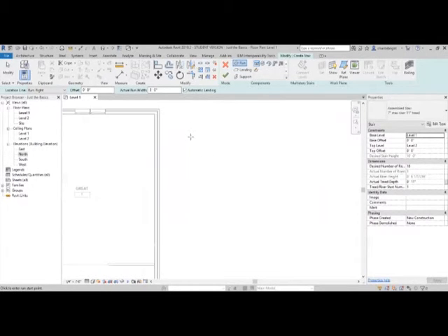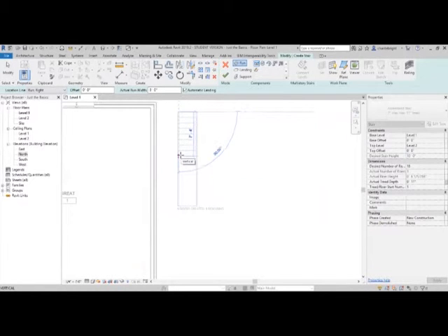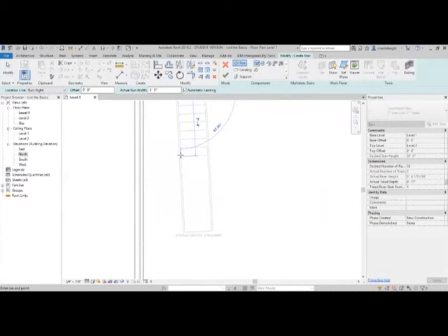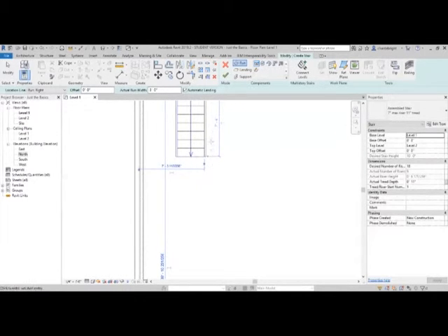So if I want an L-shaped stair, it's just as simple, and you can change where you run. I'm doing this very, very fast just to show you the different methods. I'm going to click, and I'm going to start it out. And you'll even see, right underneath the bottom, it says 9 risers created, 9 remaining. I can actually stop this, and then tell it to start again at an L shape, and I'm going to switch this to run left because that's where I ended this thing.